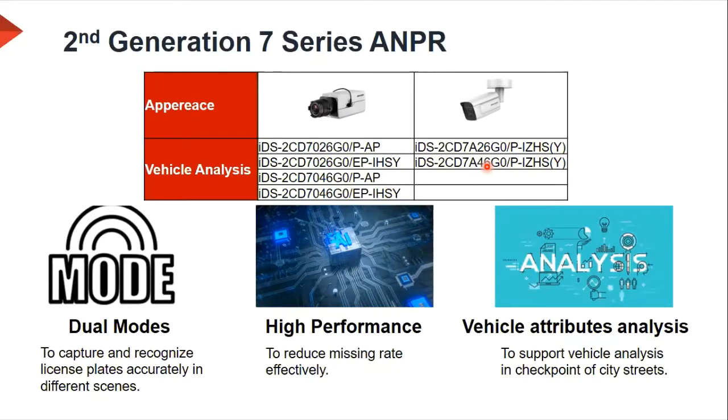Now, another thing that I mentioned is the 30 degrees. It's very, very important when it comes to installing these cameras, for sales and technical guys. The sales guys, when you do your quotes, you need to do your site inspection and make sure that you have a position to put this camera that keeps you within these distances and the 30 degrees. So be very sure about that before you quote. Otherwise, you're going to have to make some modified brackets or something like that to get within these distances and specs.